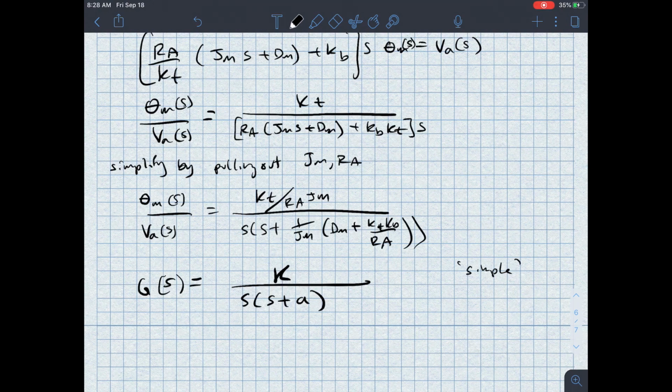If I want to find the constants, I can attach a load to my motor, and I can use my rotational mechanical systems dynamics to figure it out. To do the electrical, I can find the stall torque and the no load speed and use that information to get some of my constants. I do this using a dynamometer. But for now, what we've seen is that we can in fact simplify a motor into an expression which looks like a transfer function. And really the transfer function, even though it's strange, looks pretty easy to deal with.